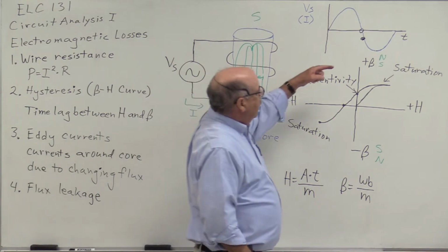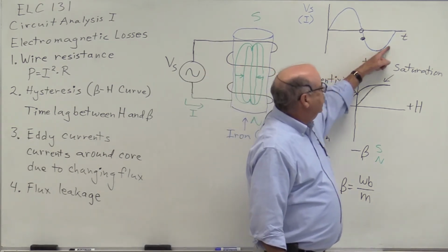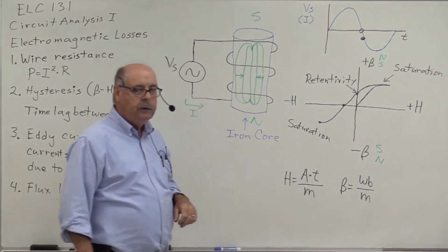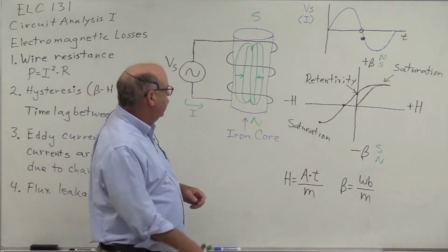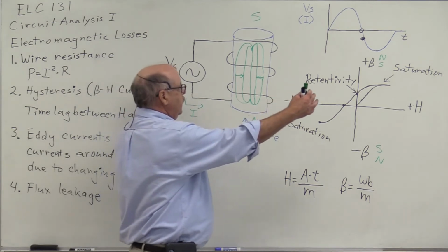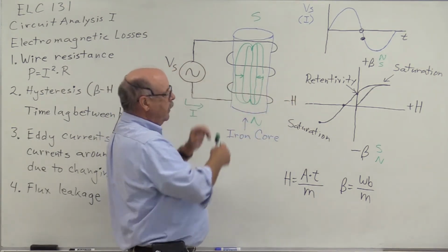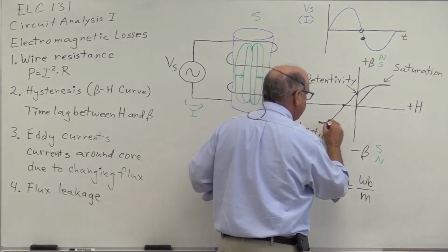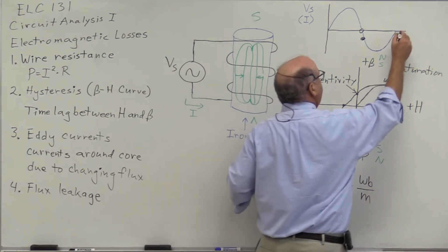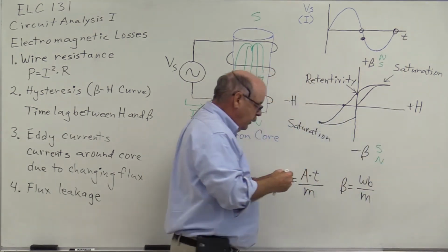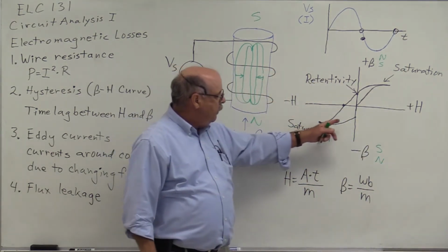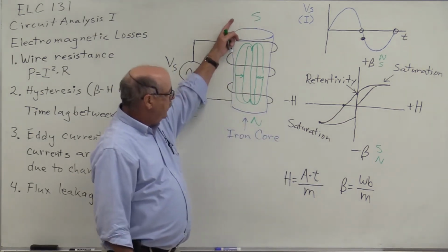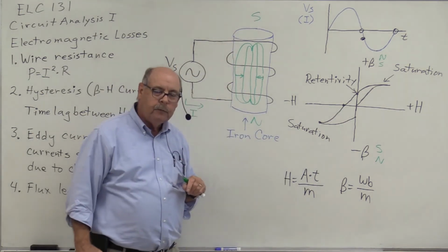Now, I start decreasing the current in the negative direction, or decreasing the negative voltage, and of course this magnetic flux is going to collapse again, and the flux will get smaller. But even when I'm here at zero, there'll be a slight amount of magnetic flux retained with a polarity of south to north.